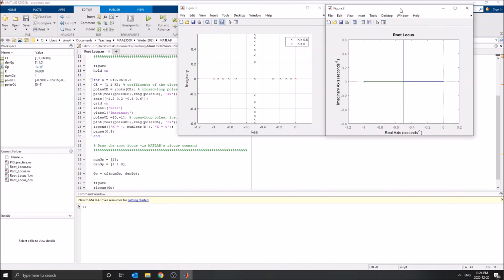All right, it's just a neat way to quickly obtain a root locus for any plant transfer function that you can think of. What's neat about it is that you can click on any point on a root locus and you're going to get several details related to that point. For example, here I've just clicked at the intersection, gives me the pole locations exactly, gives me the gain, the static gain k that drives the pole to be at that location. At that location, that gives me the damping ratio, zeta, the overshoot in terms of percentage, and the natural frequency, 0.5.